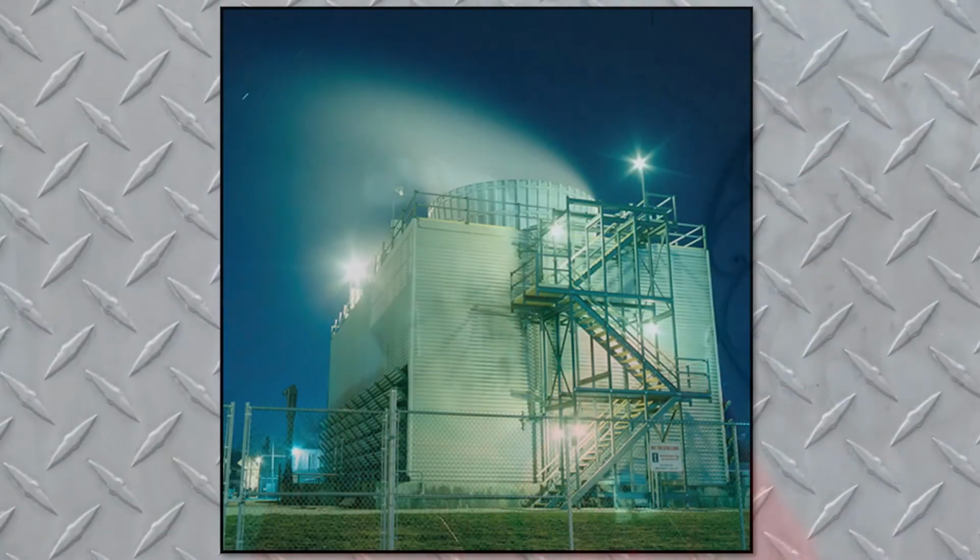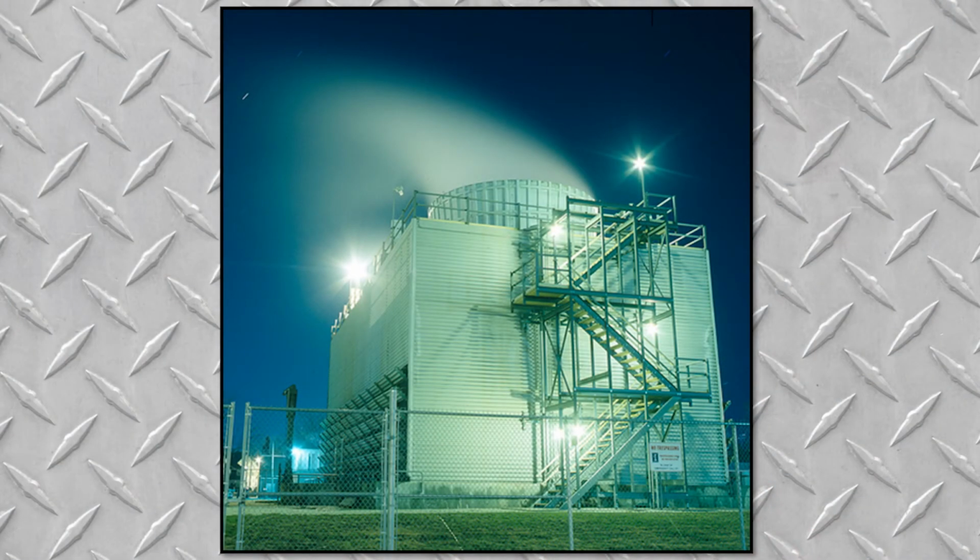Now, if you're trying to suck through the fill in order to get that evaporation and your access doors are stuck open, when you suck, most of the flow is just going to come through those access doors. So there's a lot of maintenance issues on cooling towers that you can look for. It turns out that the cost of a cooling tower is actually small in comparison to the cost of operating your chillers. So if you need to add a tower or to move a tower to a better location, it's all relatively cheap compared to working your chillers harder.